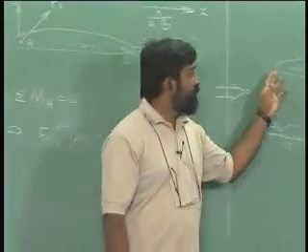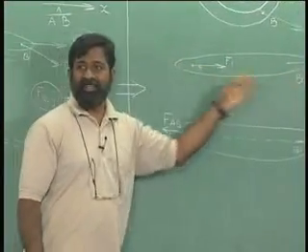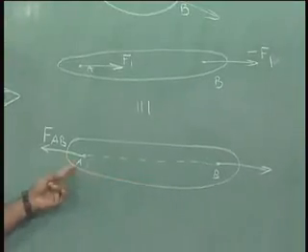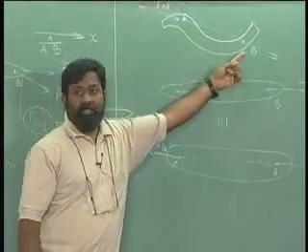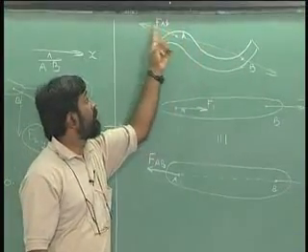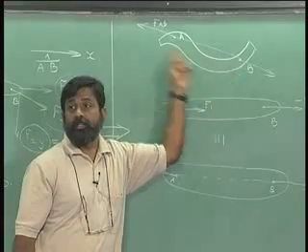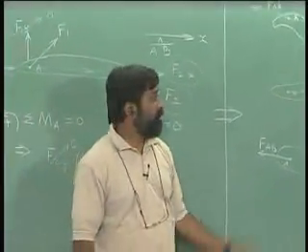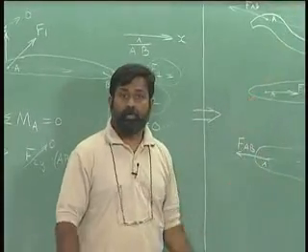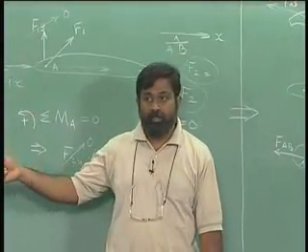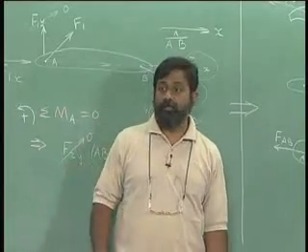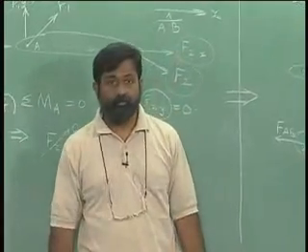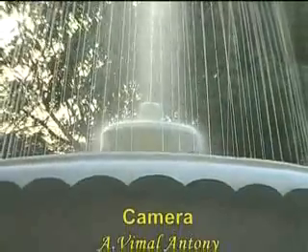Okay. If I have a straight member like this, straight body like this, we call this an axial member. If we have something like this, the conclusion is that it is along AB that the force resultants will be finally acting. Okay. This result is very useful when we come to systems of rigid bodies, and examples of systems of rigid bodies being trusses, beams, and so on.